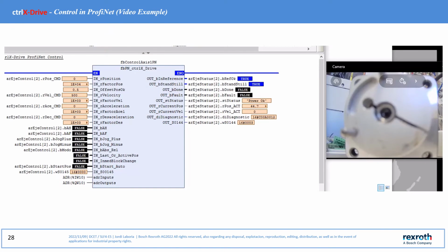In the video, you can check the operation of the IFB. Activation of the halt mode, axis with torque. In all cases, the axis status is displayed at the diagnostic output using the parameter S-0-0319. Activation of drive mode, axis with an active work mode, drive controlled positioning. Activation of both directions in jogging according to the set speed.